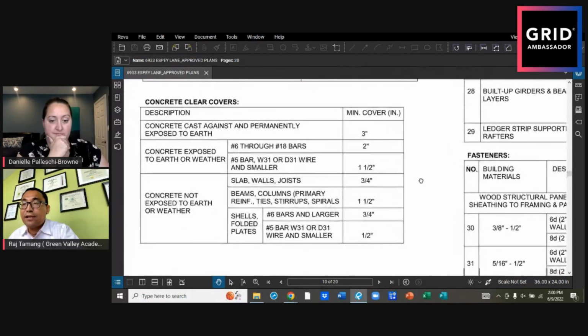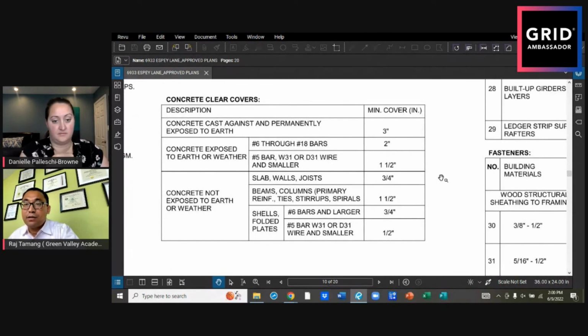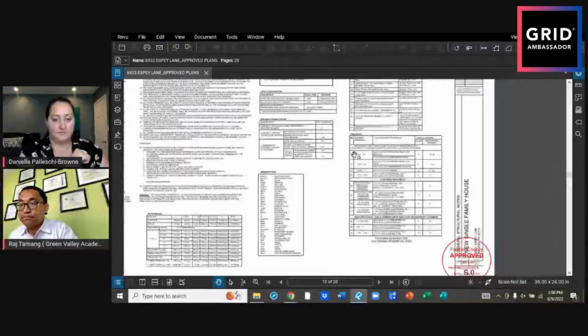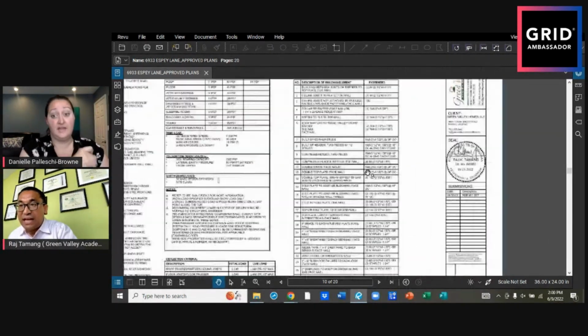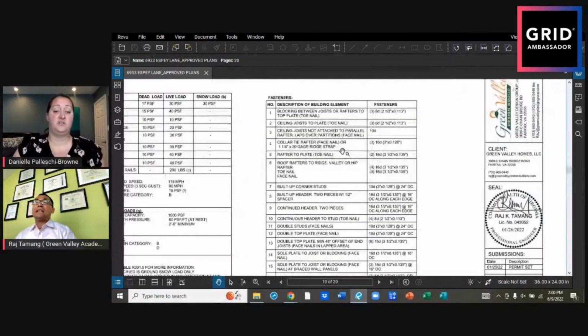Yeah, like you said, if you pour those walls and the rebars are not correctly placed, then your strength is not the same. Completely changes it. That's very true. Exactly, and it's important to know. So that's what I'm saying. You just put a rebar on the wall, it doesn't mean it's going to do the work, because if you did not install it correctly, and I've seen it all the time, I understand it.